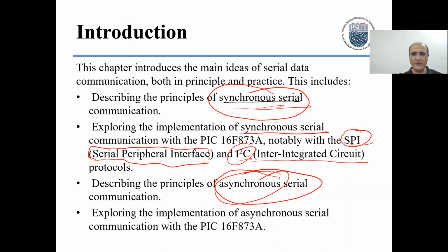For asynchronous serial communication, there are also other protocols. In this chapter, I am going to concentrate on asynchronous, and we're going to do a practical exam on asynchronous because it's the most famous, most common, and widely used. When you send data through your serial port, you send it asynchronously. When you send data through Bluetooth, you send it asynchronously, and so on. So this is the most common type of serial communication, and we're going to learn more about it, do some examples, and practice it hands-on.